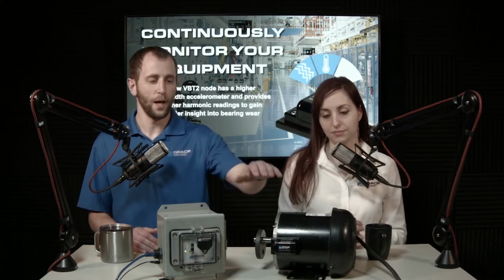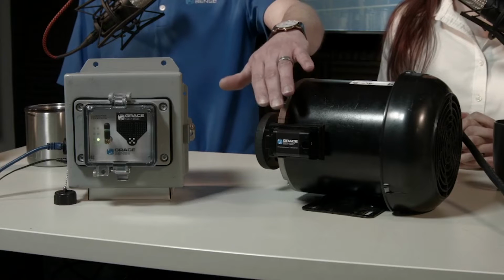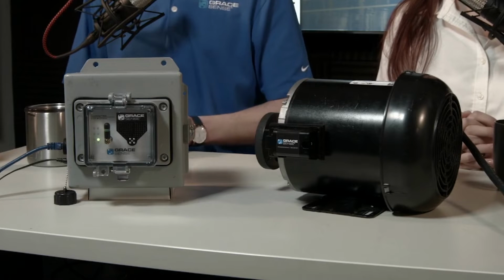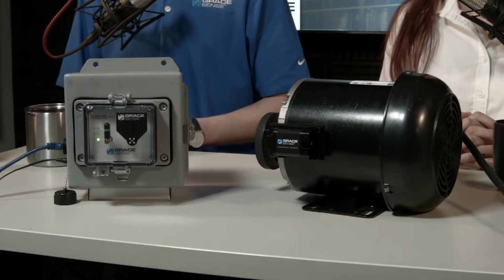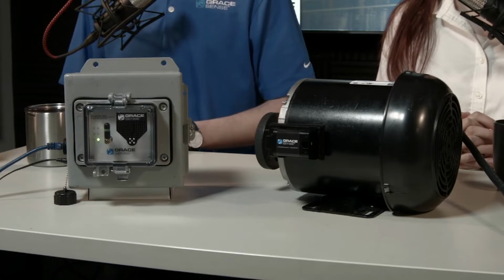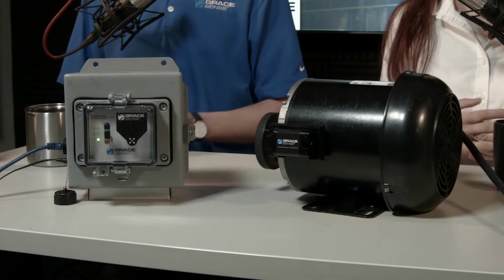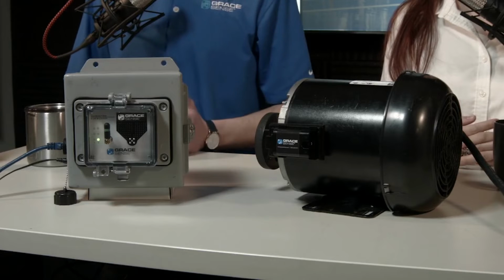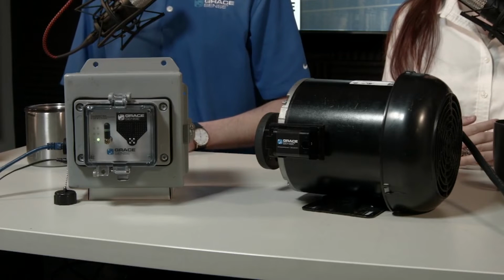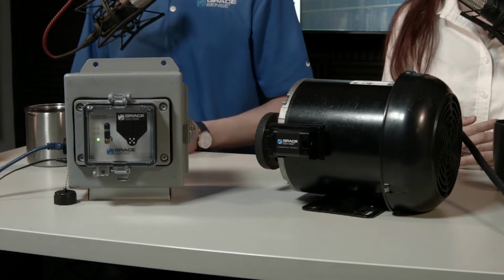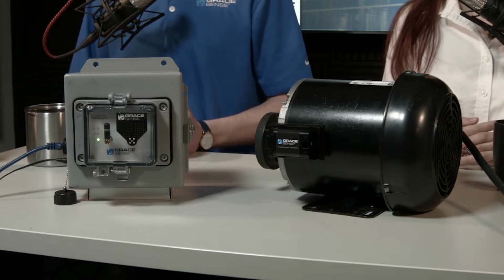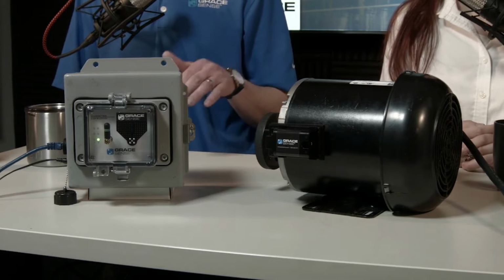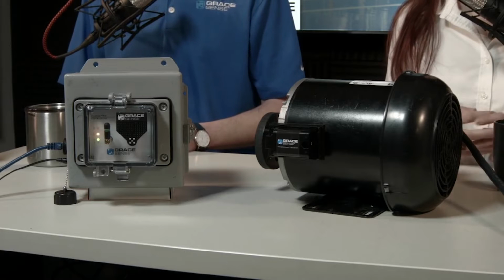Great. Just to give you an overview of the products we're going to be talking about today: we have our vibration temperature node here that would sit out on your motor or bearing, gather triaxial acceleration data, and then, as Isabel mentioned, process that and send it to a gateway. The unit we have here today is a combo gate, so it has a cloud connection as well as a PLC connection. We'll use those as a starting point, but we'll definitely get into more details on that as we move forward.